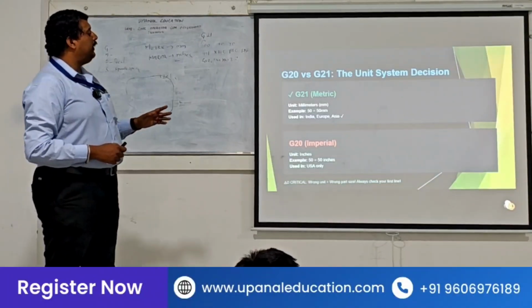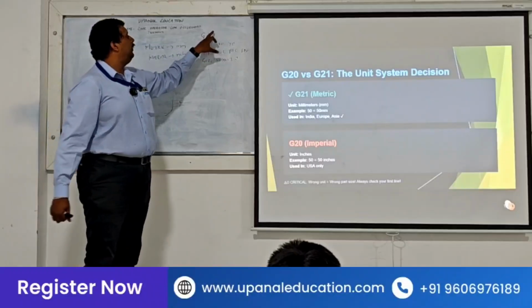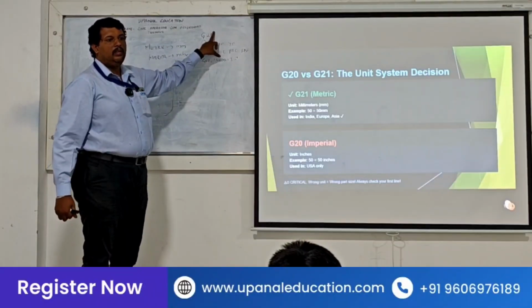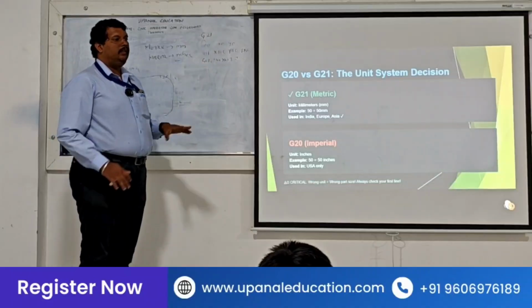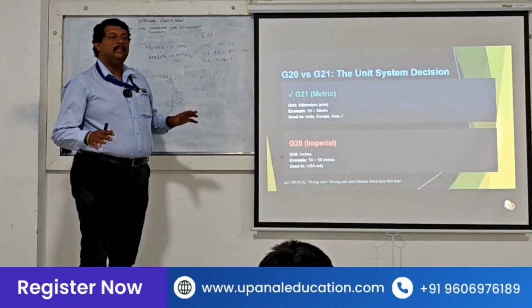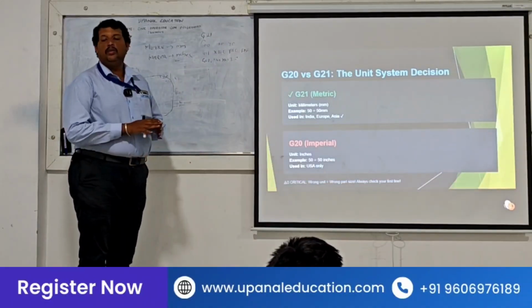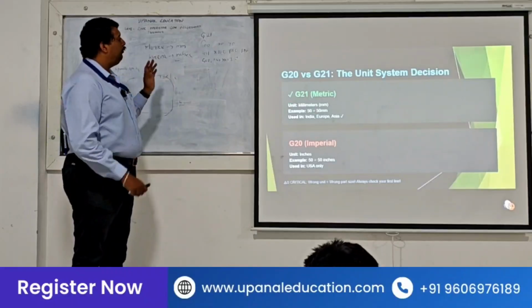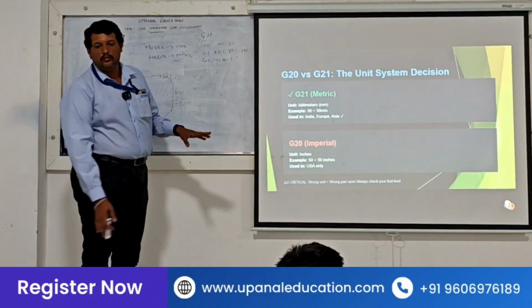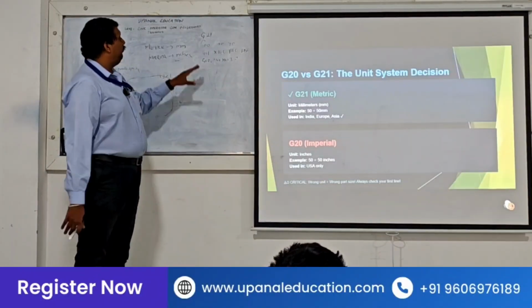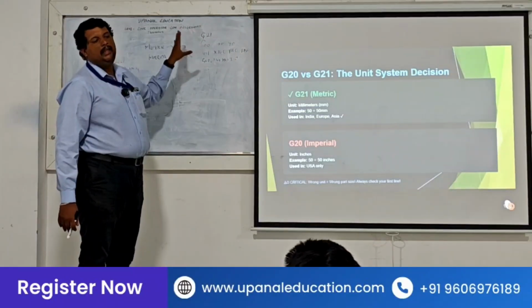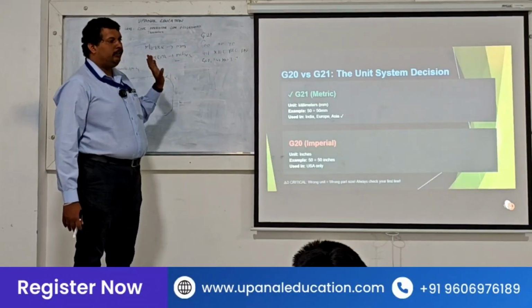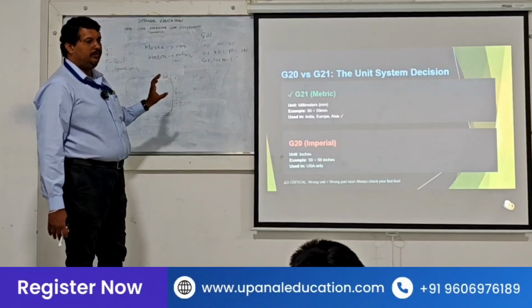So if you are giving G20 at the start, what will happen? The machine will assume that all measurements are in inches. If I give the value 50, it will go 50 inches. But if it is G21, it will go in mm. Understood? The difference between G20 and G21, you understood?